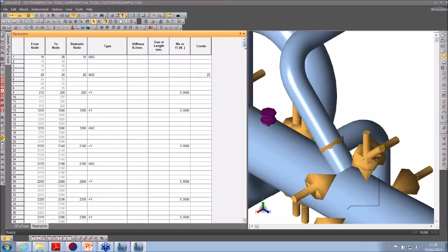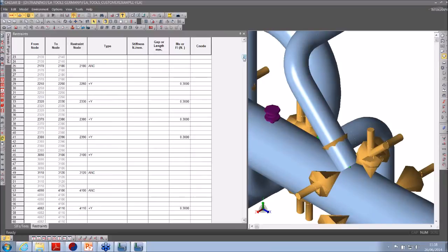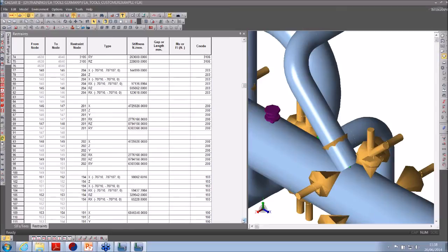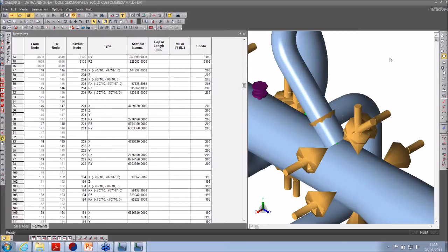Tell you, Stephen, that tends to be common for laterals where the in-plane footprint is quite a bit larger in a lateral case than it is for a normal intersection case. You simply got more pipe resisting the bending moment. Mm-hmm. Yeah, okay, yeah, I understand. And of course laterals are something that just aren't covered very well by the Appendix D, for example. At all, right. Yeah. So this is certainly more applicable data. There's no question on that for this.